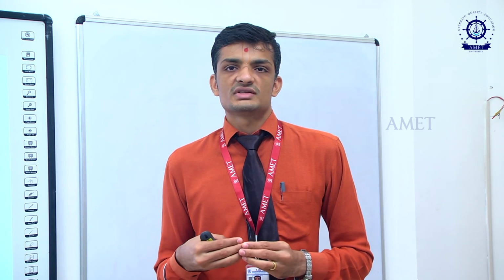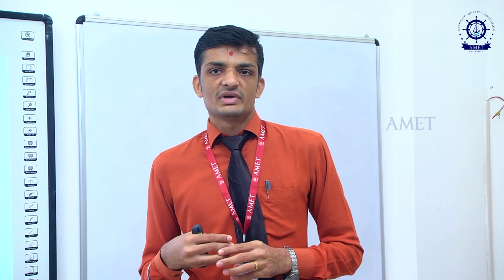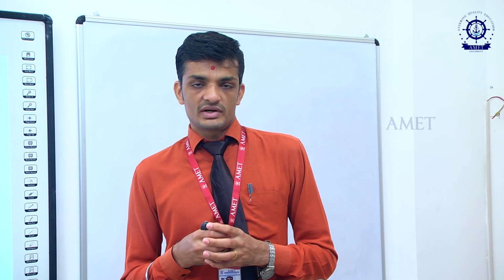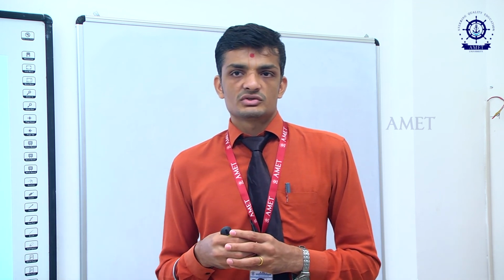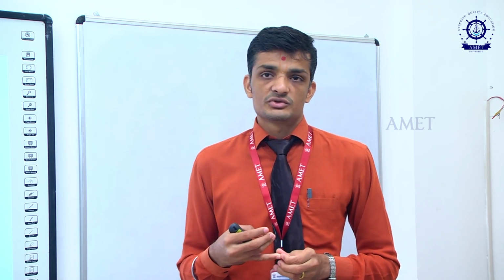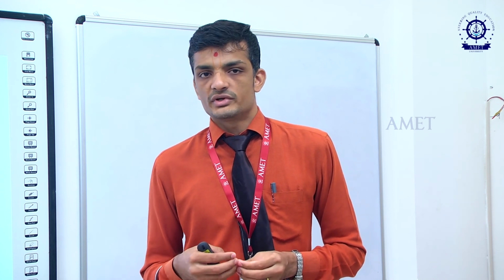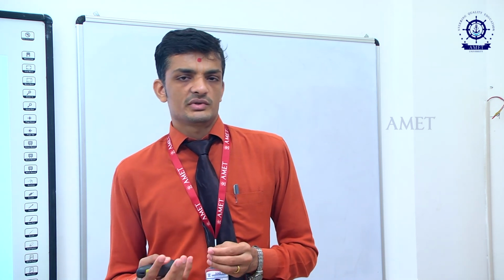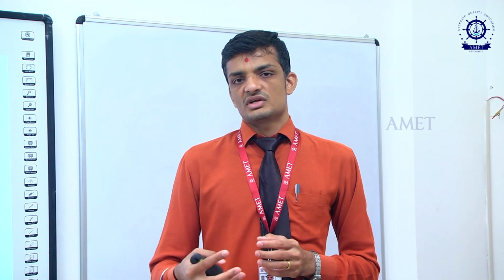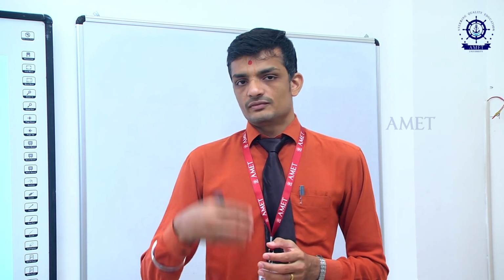Second thing is about solving algebraic equations. When you discretize or bring down the partial differential equation to small segments, actually FEA gives you algebraic equations. Those equations are put together in the matrix algebra form, and then you solve it. So that's your matrix algebra. And the last part is when you solve those matrix algebraic equations and get your computational properties. In a structural problem, that's the displacement. Once you know the displacement, you can find the other properties as well, like strain, and from the strain you can get the stress, and from the stress you get your internal forces and moment. So that's the flow, the same flow here.